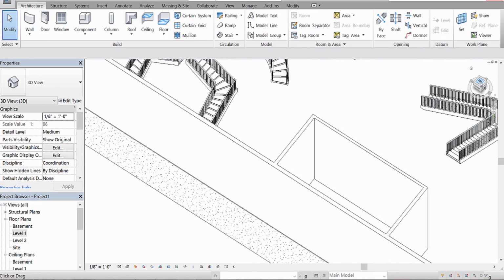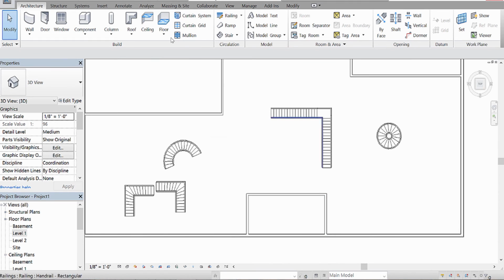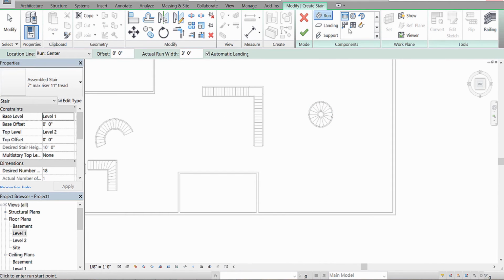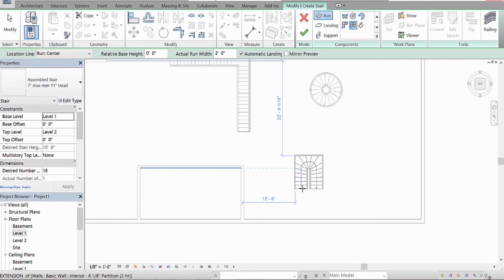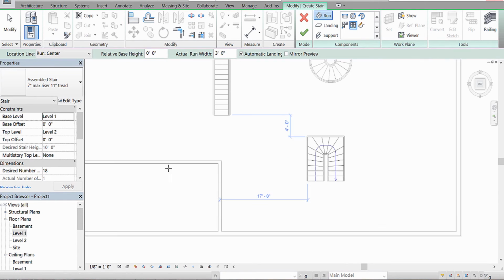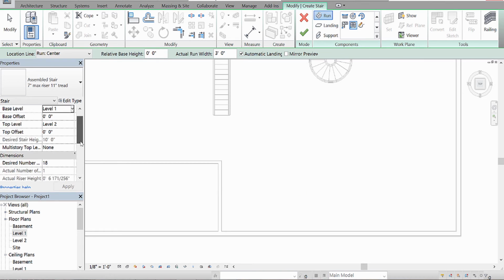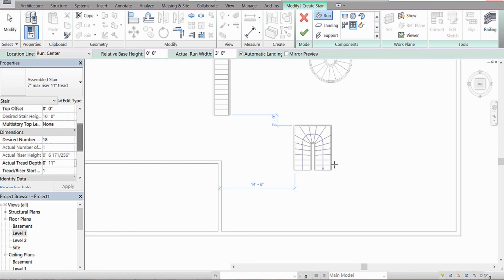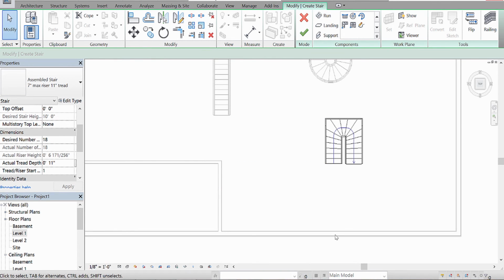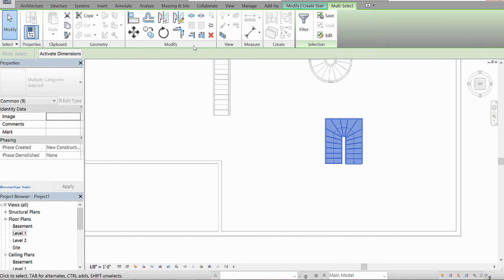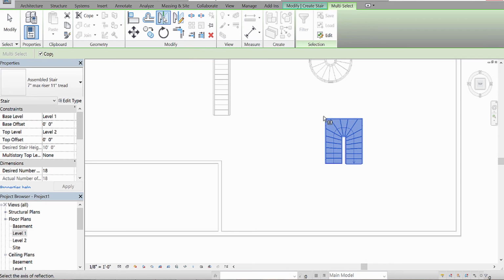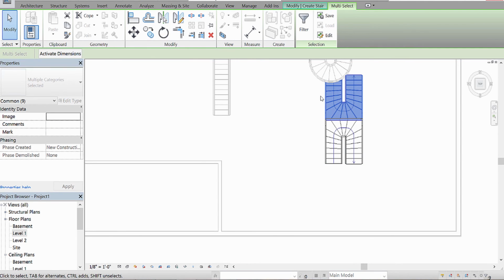And the last staircase type, if we go over to stair, is a standard U-shape winder. And this one works very similar. It's pre-made, so set up the dimensions how you'd like, and then simply apply it to the area. And if you want it facing the other direction, simply select it, mirror it over, and usually mirror is better, but okay.